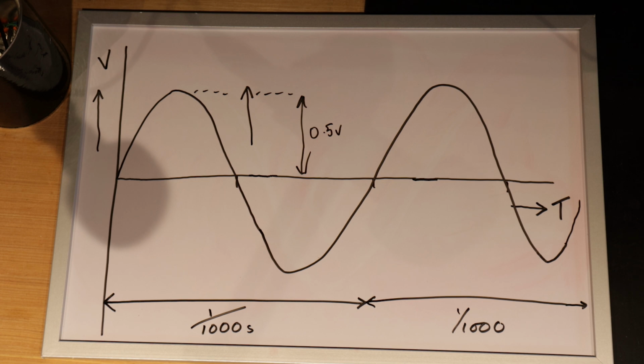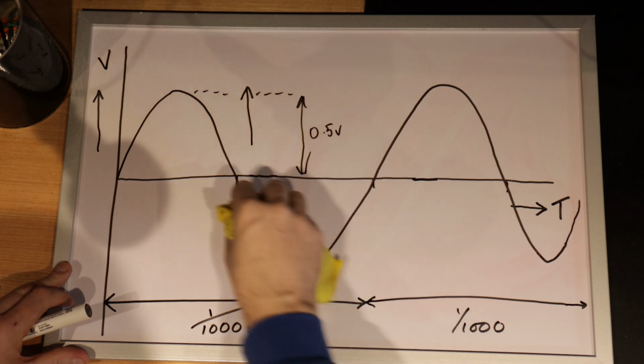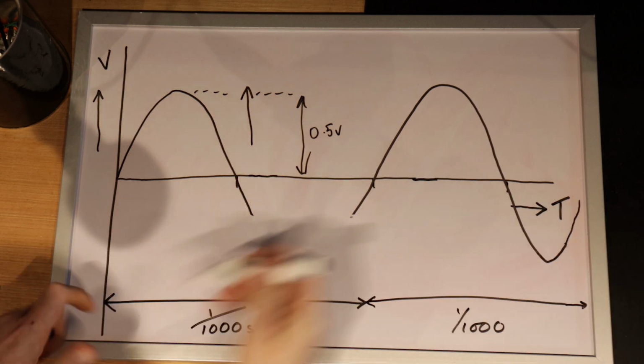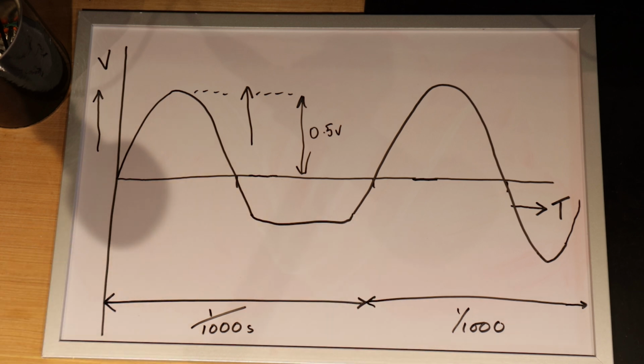It also might show you interference, and it might show you other issues. If, for example, you look at the signal on the output and you're getting something like that where it's uneven, that might point to a particular part of the amplifier, such as the phase inverter.